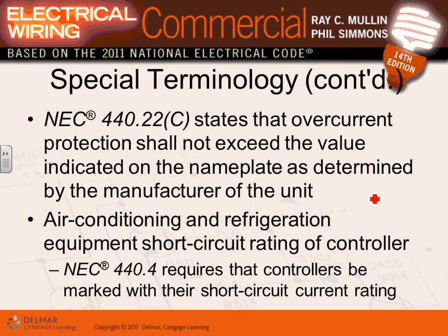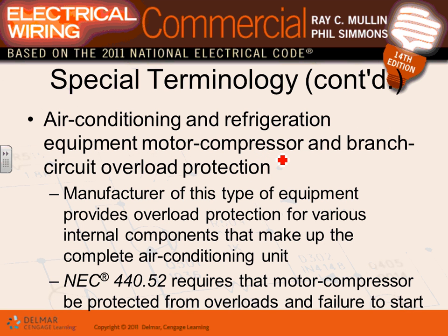Overcurrent protection device, guys. We require that controllers, which are typically installed by the manufacturer, be short circuit rated. You did the short circuit yesterday, so that tells you the short circuit withstand rating for these controllers. The overcurrent protection device shall not exceed the values indicated on the nameplate, the maximum overcurrent protection device, or 1.75. That's what we do.